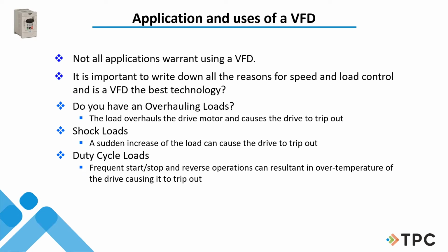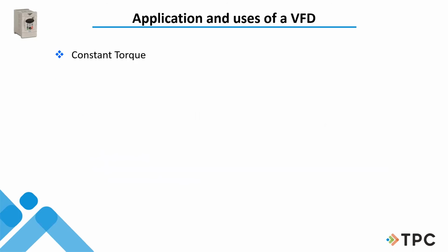And the drive turns on and off. If you're going to put a drive, a VFD, in a cabinet, you're going to create heat. So how are you going to get rid of the heat in the cabinet? Because if the ambient temperature in the cabinet gets high, the drive will trip out because the electronics are going to try to protect themselves. So how are we going to do that? And the answer is not to open the doors and let a whole bunch of dirt and dust in, because then I'm going to have other problems. So I need to know what that duty cycle is.